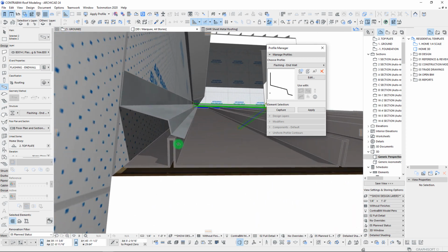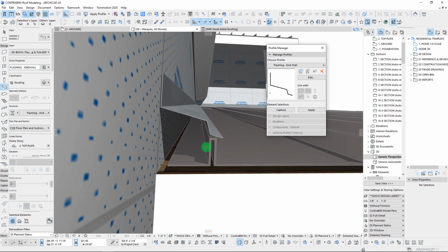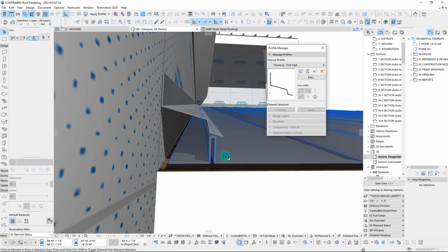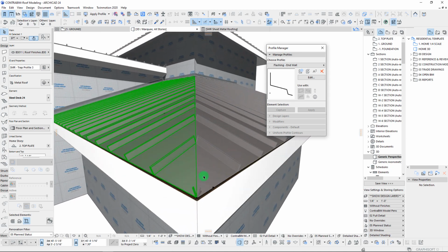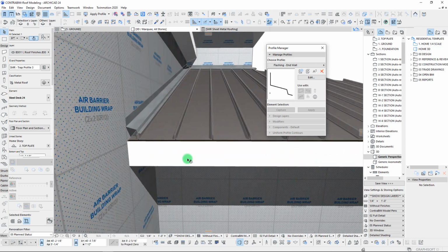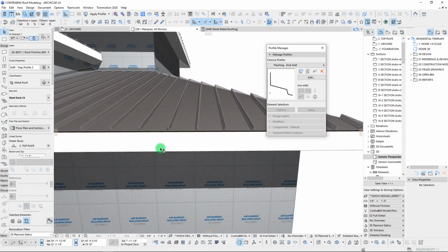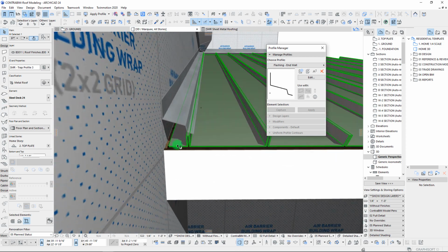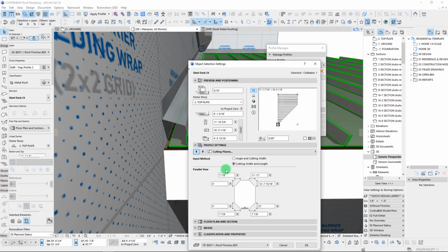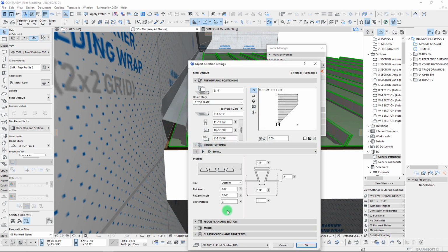Having this rib located where it is does make this a little bit challenging for that particular connection. So what we could do is give this just a little bit of an offset to bring this rib over slightly. If we go back to our object here and shift our pattern, say, 2 inches, I think that's going to move it over.